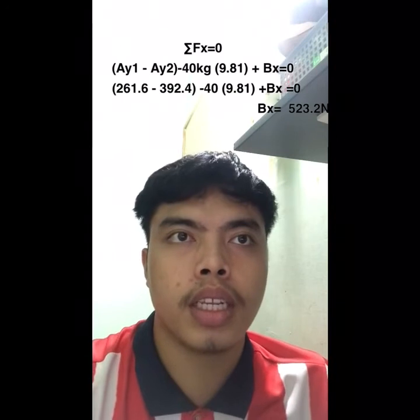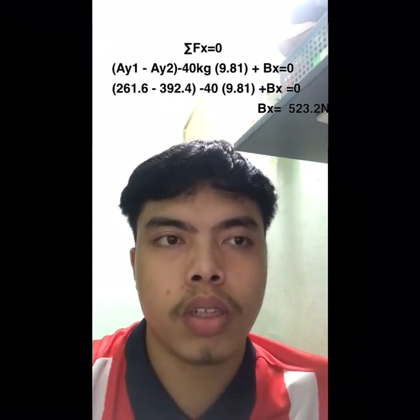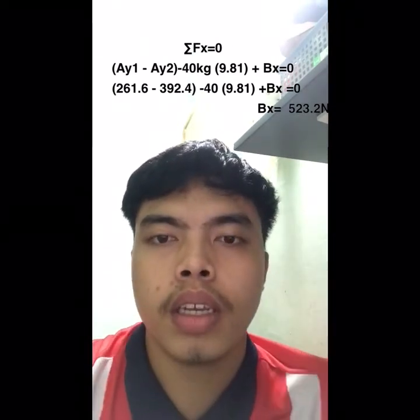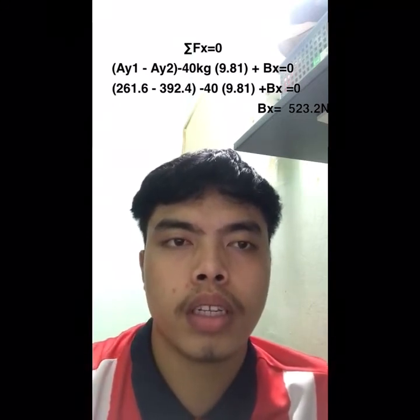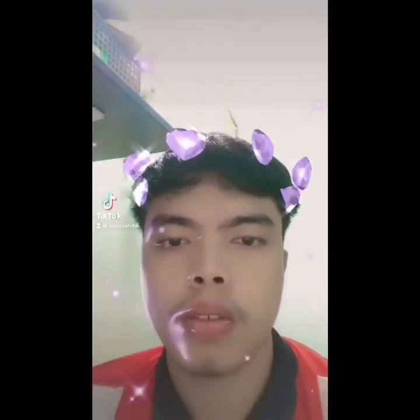For the force the man needs to push the trolley, we take the summation of Fx equals 0: AY1 minus AY2 minus 40 multiplied by 9.81 plus Bx. So we get the answer Bx equals 523.2 Newton. That's all from me. Thank you. So I will pass to the next part for Hasri Nartisha Ayuni.